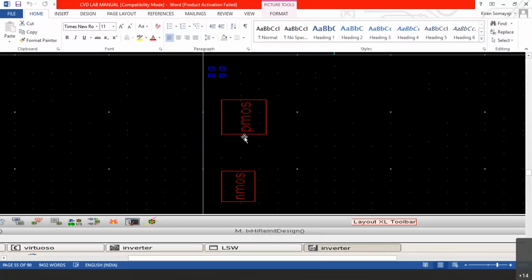Then below that you can see the PMOS and NMOS. That means the tool has taken the PMOS default layout which is already present with the tool's library. It contains both NMOS and PMOS default layout. So we are not going to make the layout of the devices as such. We are going to make the layout of the complete circuit of the inverter using the devices' default layout.